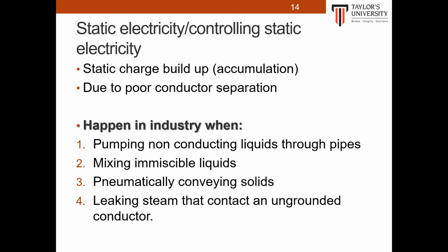Common industry examples are pumping a non-conductive liquid through a pipe, mixing immiscible liquids, pneumatically conveying solids, and leaking steam that contacts an ungrounded conductor. All this static charge in these examples accumulates to develop large voltage. Subsequent grounding produces large and energetic sparks.